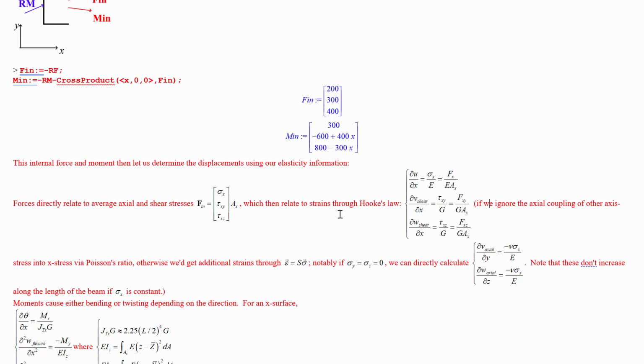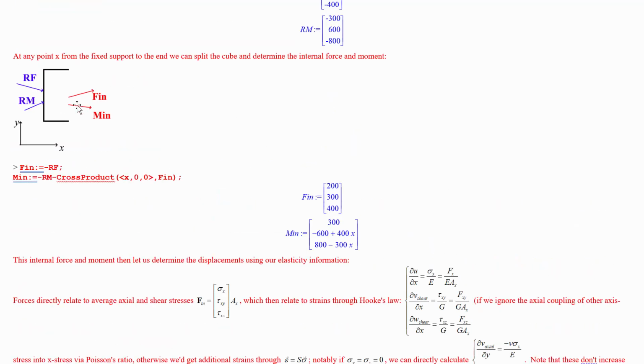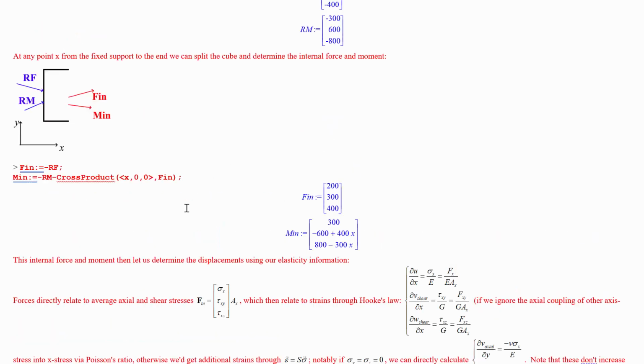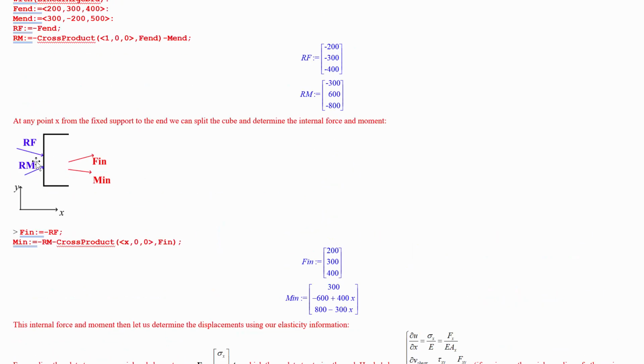According to the shear stress divided by the shear modulus, that'll tell you the shear strain. Now, the shear strain, how do we turn that into displacements? If we assume that the surface has no x displacement shear strain, which is reasonable because the back side is fixed, so shear will be causing just this sliding